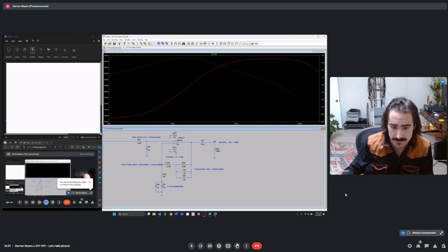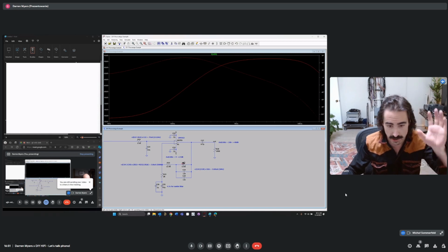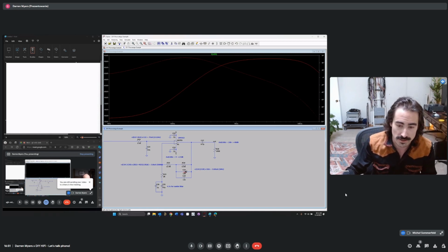So it's that RC that's really taking an effect. But we have to look at the components around it and how they're interacting with the impedances at certain frequencies. So in order to do that, our equation becomes R23 plus R25 in parallel with R26 times, and that's our R, and then our C value is going to be R24 in parallel with R29. And that, with capacitors, we just add that value.